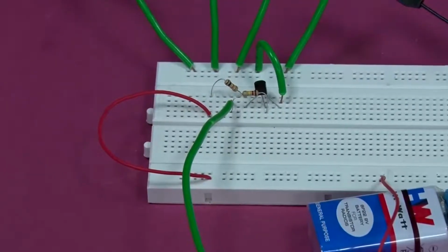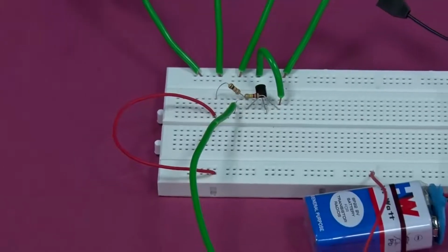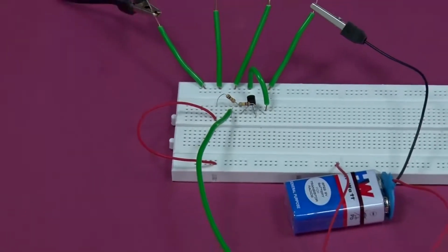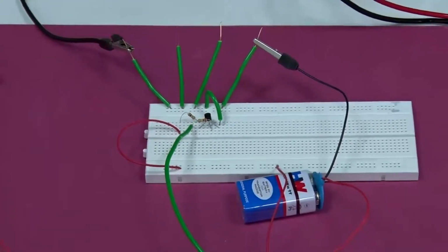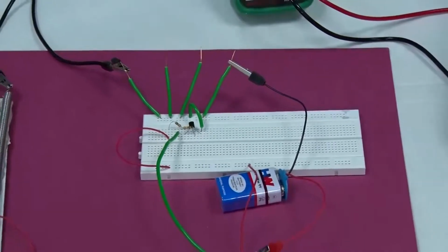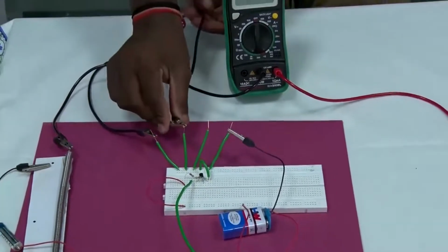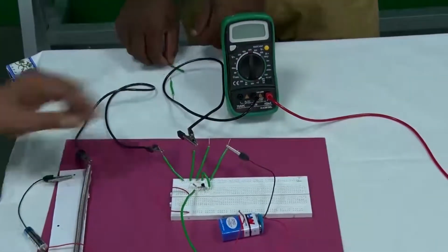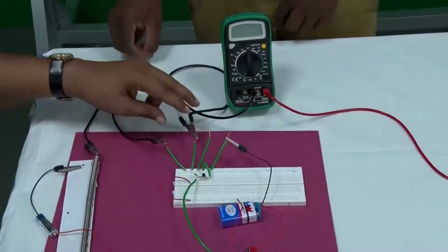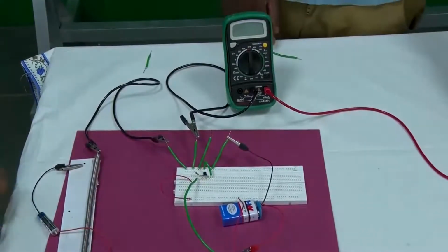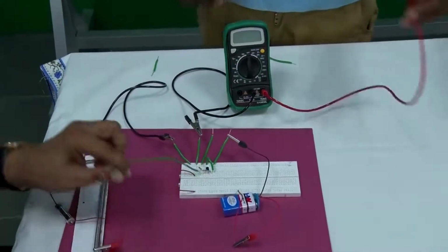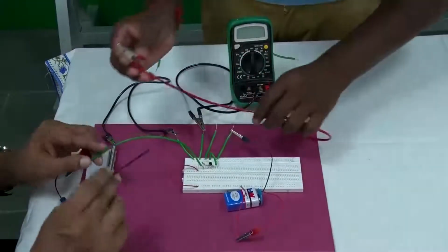Now, we have to add the multimeters for measurements. One multimeter is needed for the input side. The black terminal should go to the ground 0, yeah, the black terminal is going to 0, good. And then the red one should go to that variable point. Where is that variable point? Here. So, that red terminal should be connected here.